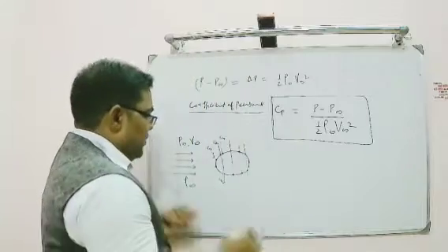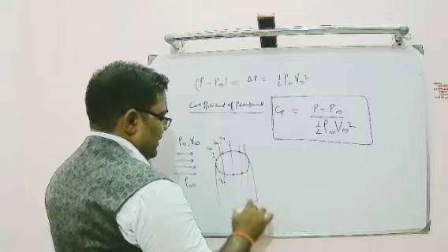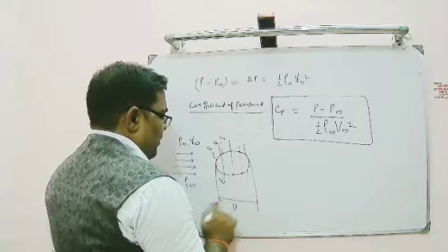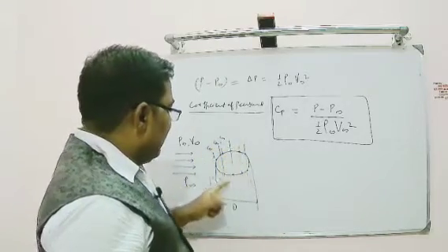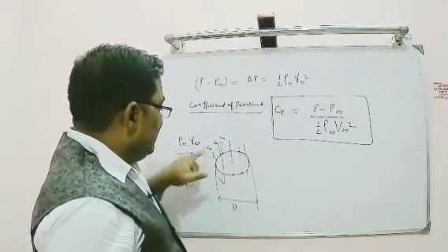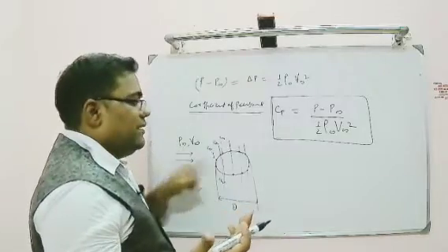Whenever I'm talking about the entire length of the flow, this is the length of the flow. If it is a circular cylinder, then this diameter is my chord length. Usually we define it as the length of the flow. So the moment I know the Cp values at different locations, I use this formula. If I am writing Cp1, that means at this first port, what is the pressure value, minus P infinity, divided by half rho.